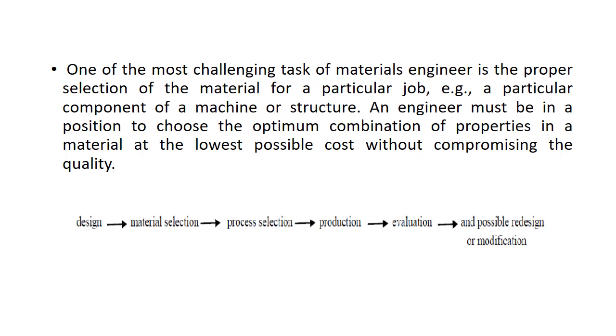Next, identify the material selection criteria. Material selection criteria are specified material properties derived from the requirements identified during the previous step, that is, the identification of design requirements. For example, for a component that must support a specific load, the minimum yield strength required for the component material can be determined. This will be one of the material selection criteria.